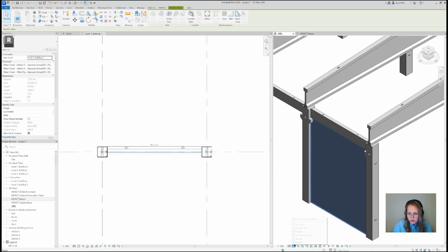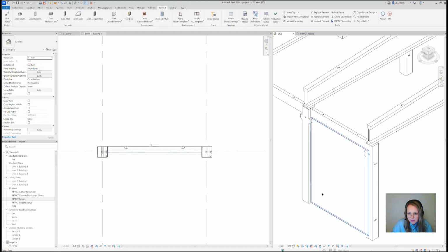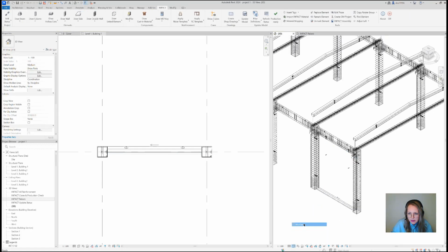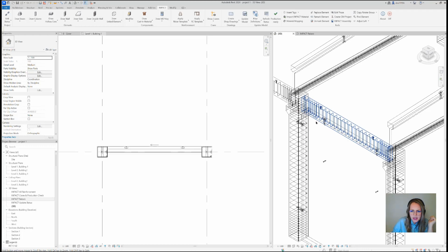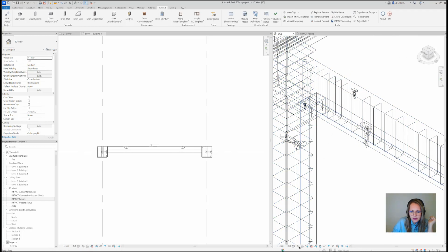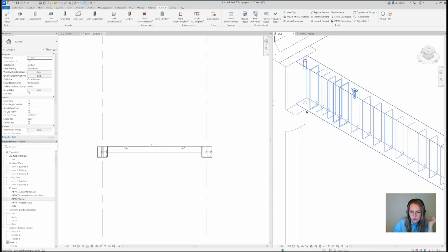What I wanted to notice is, if I do like this, probably here you can easily see that Impact has also inserted, based on some definition rules, the bracing and the lifts that we have defined in the element definition. So this is happening automatically if you turn on this in Impact, and it's based on calculation of the weight. Okay, I have the wall, but you can see I have a collision that I need to solve.